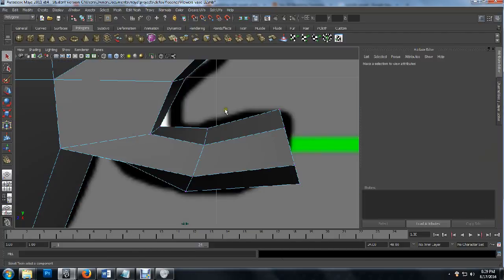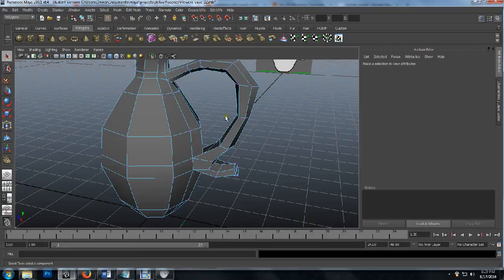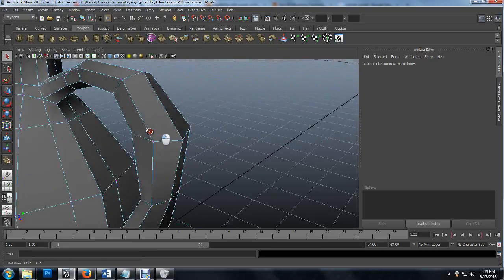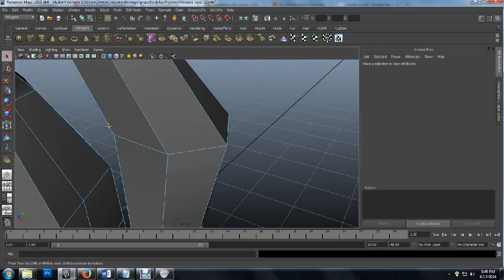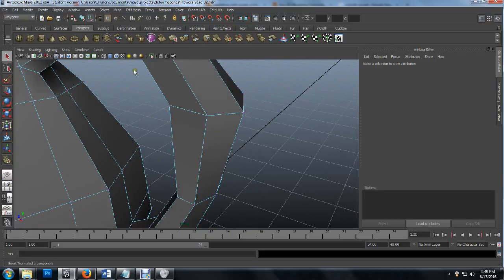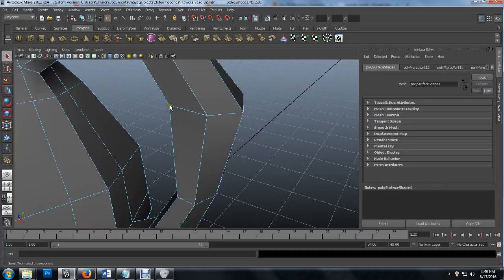Come here on the side. Actually, no, I won't do it that way. I'll do it this way. This way you can get an idea of how to do this anyway. I want to do this edge. I could Marquee Select, but I can't see what's on the other side. So to make sure that I'm getting the edge that I want, I'm going to grab this vertice, double click, and it should grab all of them. Hit R, and I'm going to resize these.